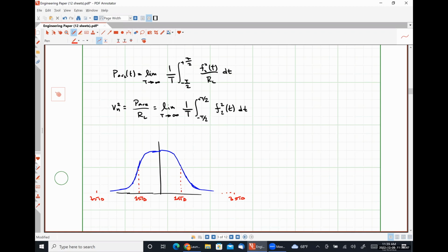So we don't know what the instantaneous value of the noise is, but we have a pretty good idea of the range of amplitudes that we should experience, and we know what their general distribution is going to be. So that allows us to not be able to predict the instantaneous value, but have a relatively good understanding of what our design constraints will be, because we should expect our noise to not exceed particular boundaries except in extreme cases.